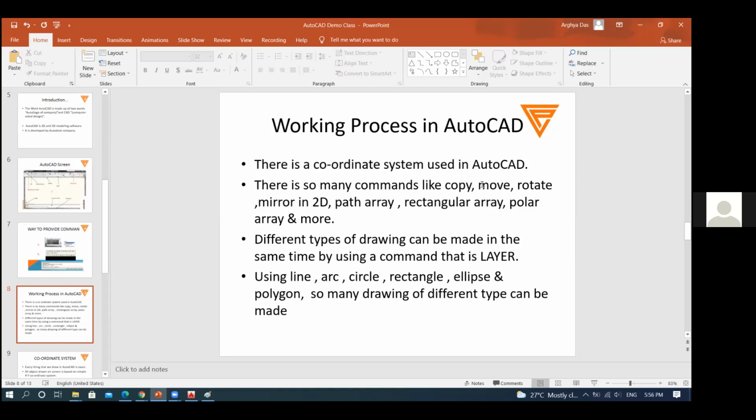If you want to move anything from one drawing to another drawing, say you have already drawn the foundation of a building and you have to draw another building, but you want to keep the old foundation unchanged, then you can simply copy the old foundation from the old building to the position of the new one by using the copy command or the move command.